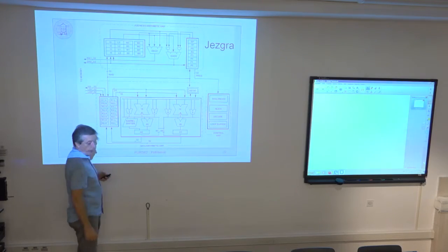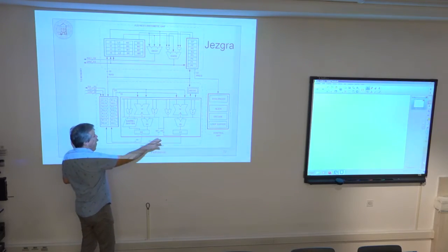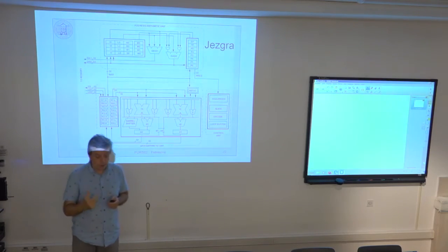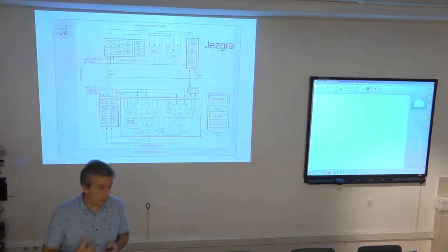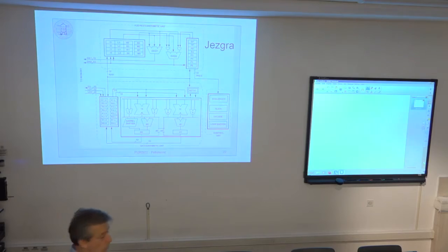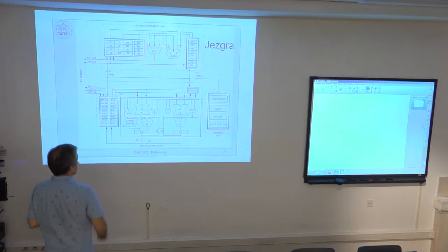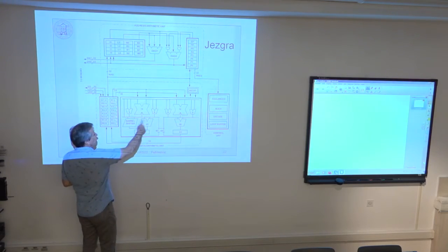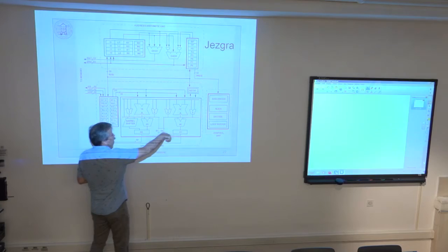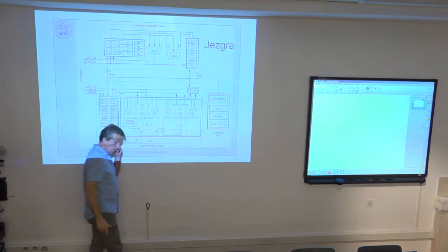Since I have two multipliers, A0 and A1. Actually, it is the same 8-bit extension as we had on this described architecture. So 32 bits for the result lower word and upper word, and finally 8-bit extension, altogether 40 bits, that can be accumulated in this accumulator as well as in this accumulator.